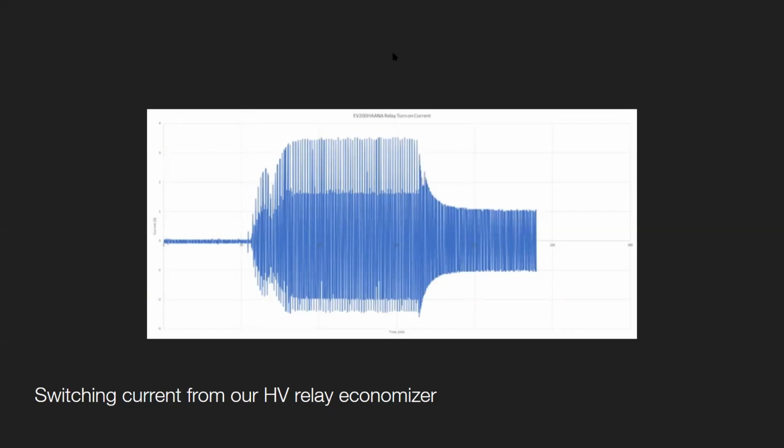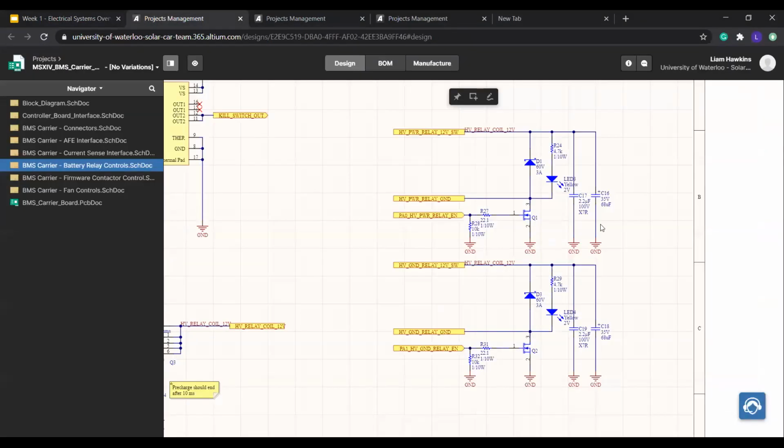So to provide this high current, we have these large capacitors here. And like I said before, the current you can draw from a capacitor can change very quickly. So you can draw current very suddenly from these capacitors, which helps to close the relays, because otherwise the power would be coming from power distribution, there's a lot of wires and inductance. And then power distribution might also go into an under voltage fault if you draw too much current from it.